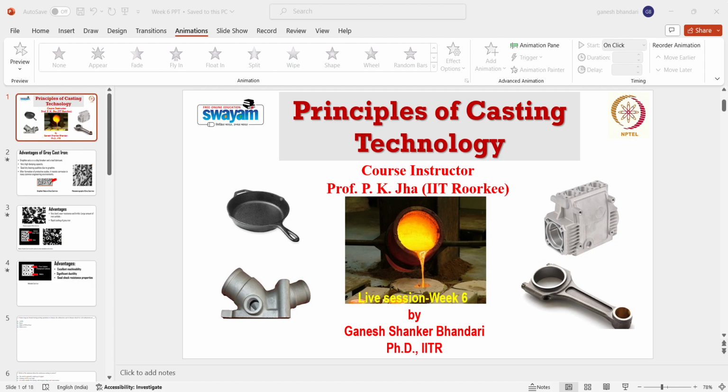So you are going to add alloying elements like cerium or magnesium. In major foundries, they use magnesium and cerium as alloying elements for making these spherical carbon nodules in the cast iron, and it possesses very high ductility compared to other cast irons.